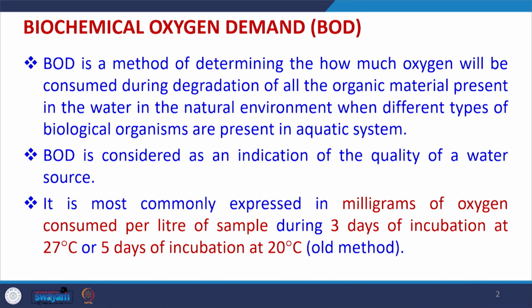Now, BOD is expressed in milligram of oxygen consumed per liter of sample. Earlier the tests were conducted for 5 days with incubation of all the samples at 20 degree centigrade. However, recently 3 days of incubation is done and the water samples are kept at 27 degree centigrade. Today we will learn how the BOD test is conducted. That will come later in today's lecture.